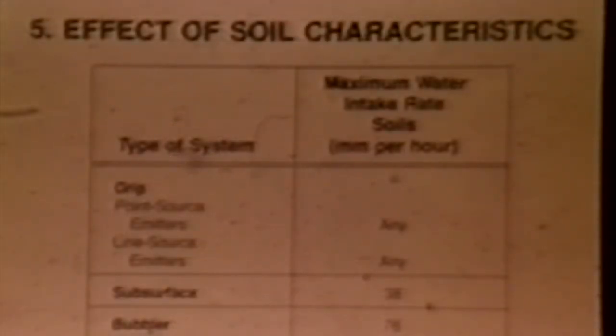The rate of water absorption of the soil will determine the number, discharge rate, and spacing of the emitters and, to some degree, the type of system to select. If the soil absorbs water slowly, select emitters with low application rates. However, low absorption rates are generally associated with fine textured soil. In this soil, water will move farther from emitters, thus a smaller number of emitters are required per plant. Just the opposite is true with most coarse textured soil. Thus, in coarse textured soil, use a larger number of emitters per plant to meet the water needs of the crop.